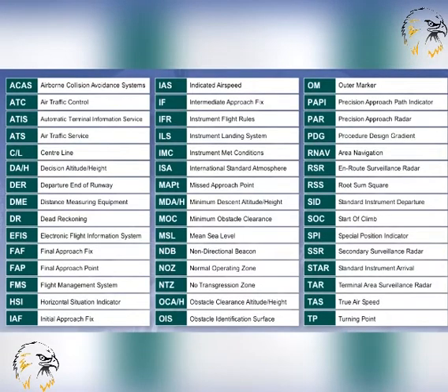If you are required by ATC to divert to an aerodrome with which you are not familiar, and you are not in possession of the appropriate printed representations of the procedures, or plates, then ATC will read to you all aspects of the procedure.